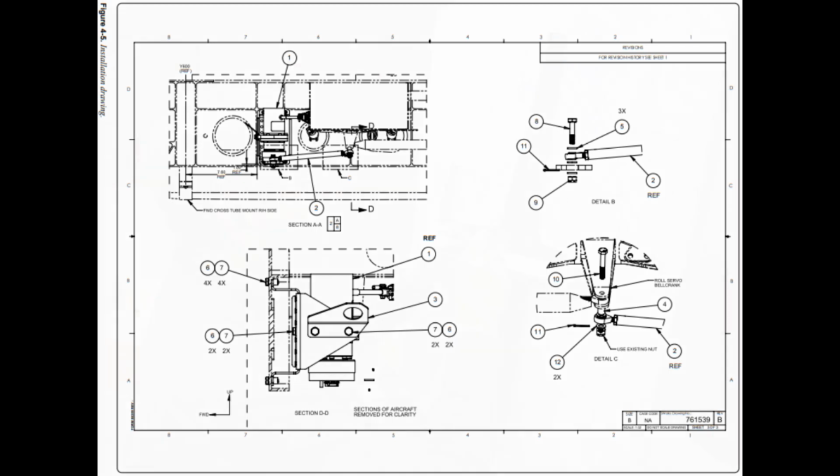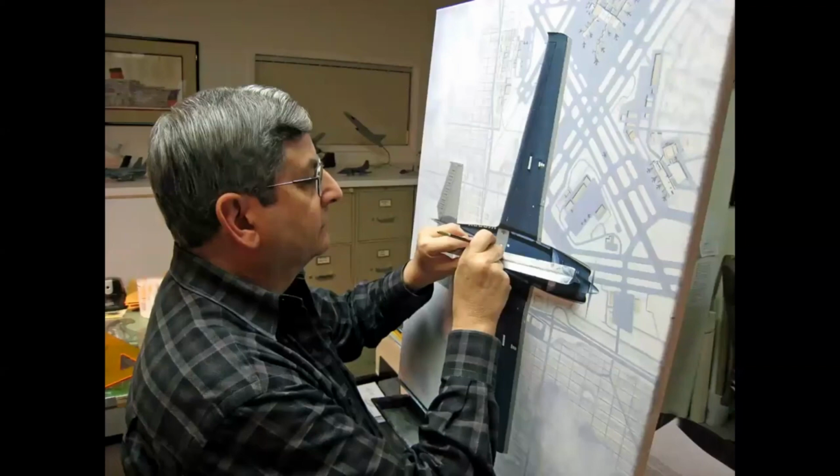Sectional view drawings. A section or sectional view is obtained by cutting away part of an object to show the shape and construction at the cutting plane. The part or parts cut away are shown by using section, cross-hatching, lines. Types of sections are described in the following paragraphs.